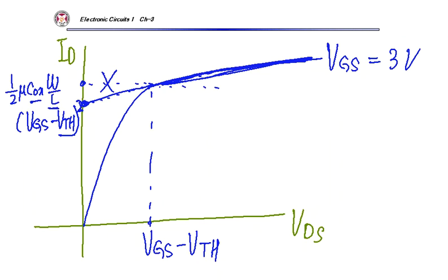So you measure, don't use a function generator to measure current. You just change the supply voltage one by one and then measure all those currents, okay? You can use your diskette, 3.5-inch diskette, or so, to monitor those currents.